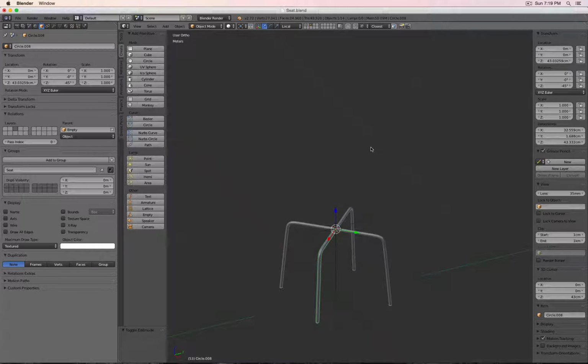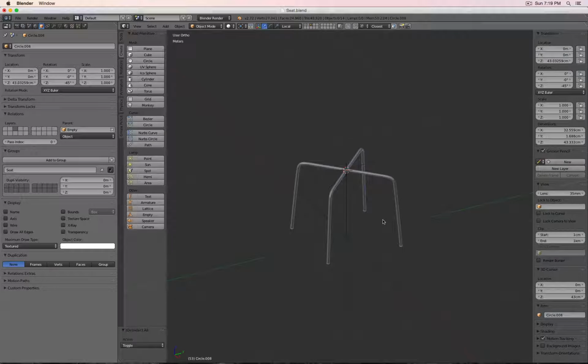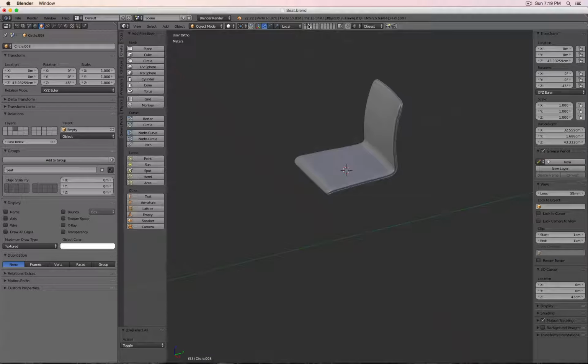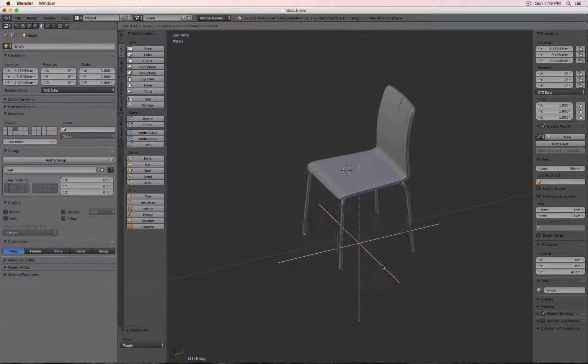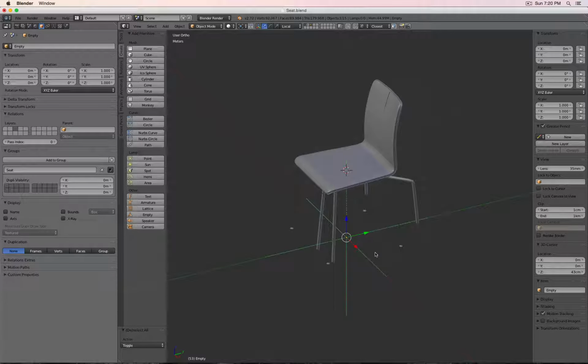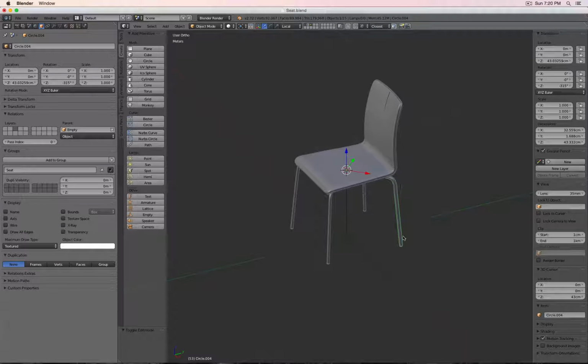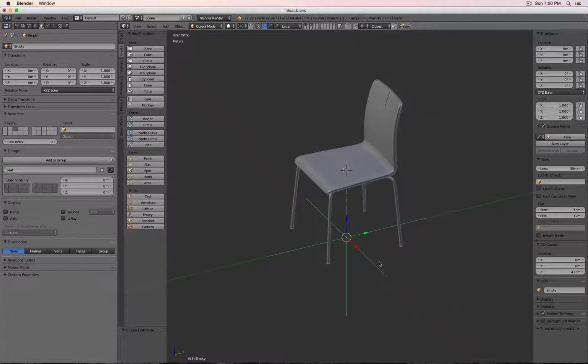And now you might ask yourself, well, why did I do all these groups, etc.? The main reason is I can import or append actually this group. This will bring in everything, including those two design shells I made. And then, for example, with just selecting the empty and moving it around, you see I can update and reposition my whole object, rotate it.